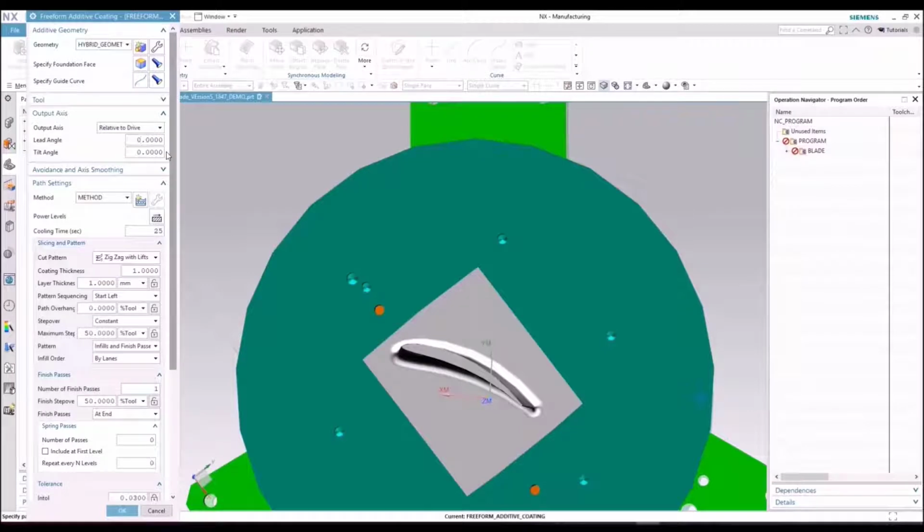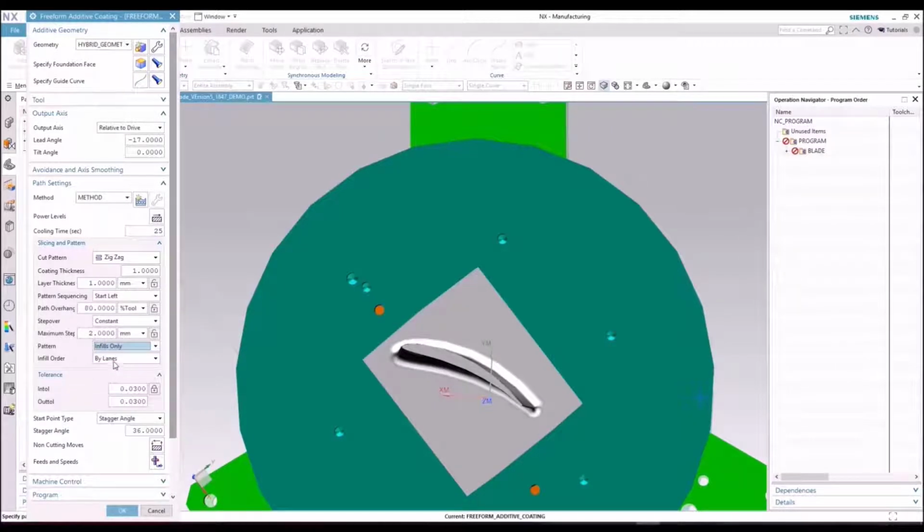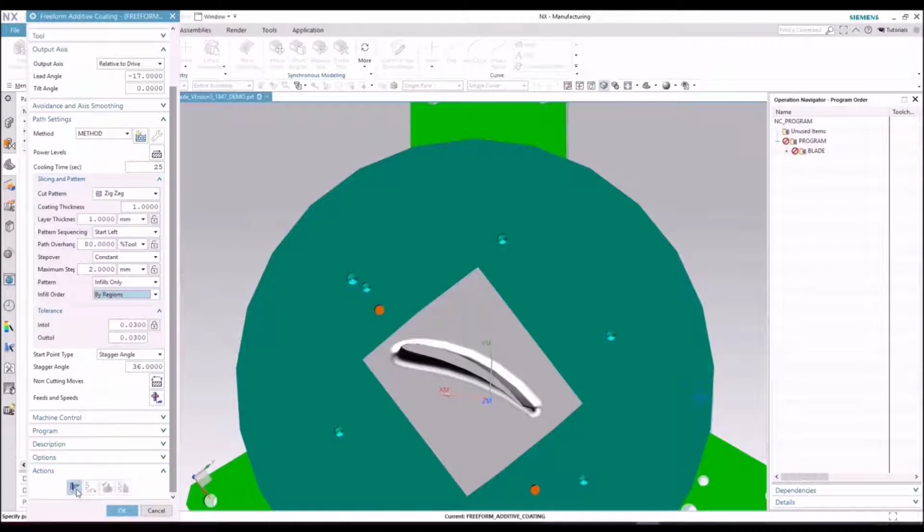Once the surfaces, guide curves and tools have been selected, the path properties can be determined. The tool path strategy needs to be defined in accordance with the given component shape and the surface topology. In our example, the surface region to be coated is homeomorphic to a cylinder surface. The spray tool is to be moved primarily in the circumferential direction around the airfoil. Secondarily, it is to move in vertical direction following either a helical line or a vertical stack of tracks, each alternating in direction.